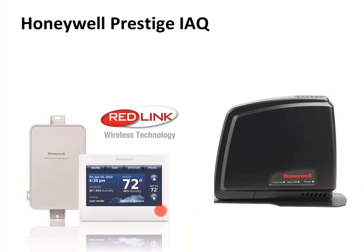So the reason it has 2 wires is that it needs power, because most LCD displays are fairly power hungry, so you're not going to be running these things off of batteries. So it does need 2 wires for power, but that's all it's doing, 24 volts. Then the stat wirelessly talks over here to the equipment interface module, which is this gray box on the side, and that sits down next to your furnace or up near your rooftop unit, depending on which scenario you have, and that has all the regular HVAC wiring. So G for fan, Y1, Y2 for cooling, W1, W2, R and C, and all that usual stuff.